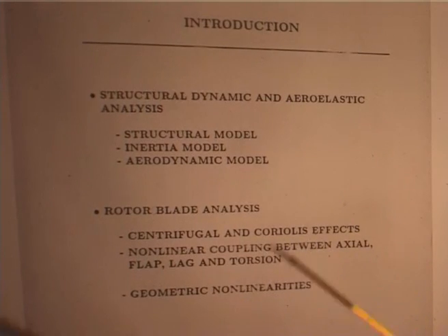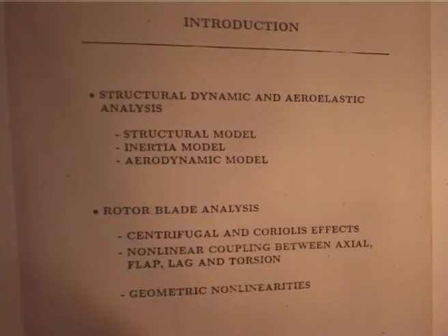These are because of rotation, okay, and this you cannot neglect. So, this is the difference between a beam which is not rotating, which you study in your aircraft structures 1, but here is a rotating beam. So, you have centrifugal and Coriolis, both will come because of the deformation.